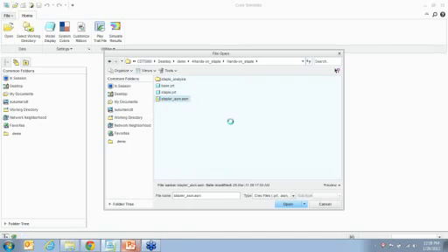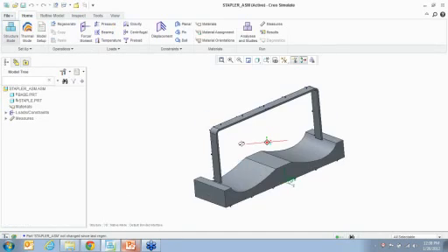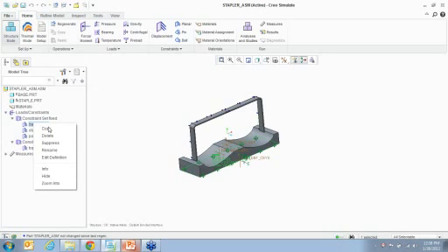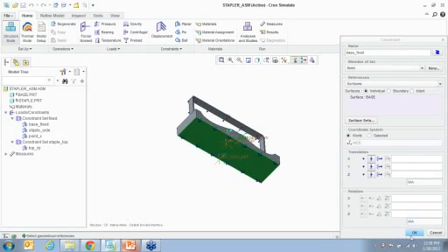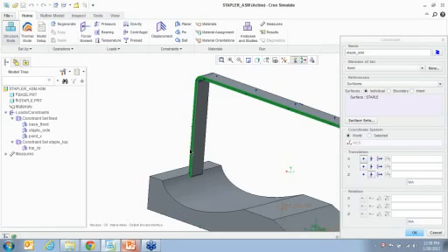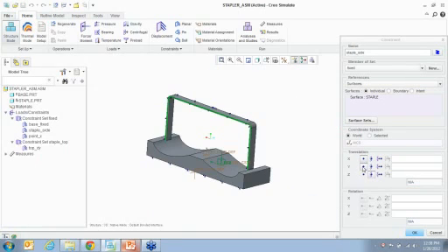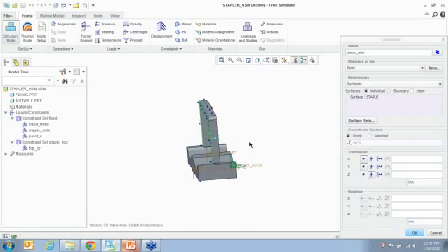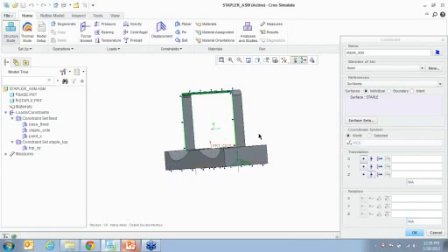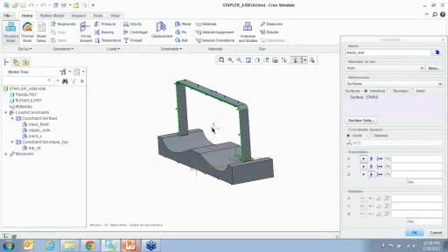So we have our stapler assembly. All right. So I want you to see right now I have a few loads. Few constraints. So I'm going to go base fixed. You can see that I've fully fixed the base of it. I'm going to pick the side of this stapler and say I can only translate in the X and Y, and I'm fixed in the Z. The Z direction is this way. You can see which way the Z is right here. So it can only go up or down, right? But it cannot go this way.